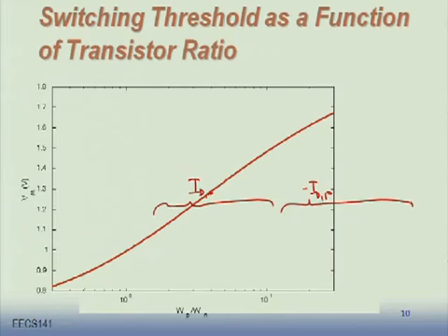What's the switching threshold if WP is equal to WN? There will be a point somewhere over here on the graph, somewhere around 1 volt, a little bit more than 1 volt. Would this yield symmetrical noise margins? No. Where would we like to have VM to be? Somewhere around half the VDD value, then it will be really symmetrical margins. Where is half the VDD value? 1.25.